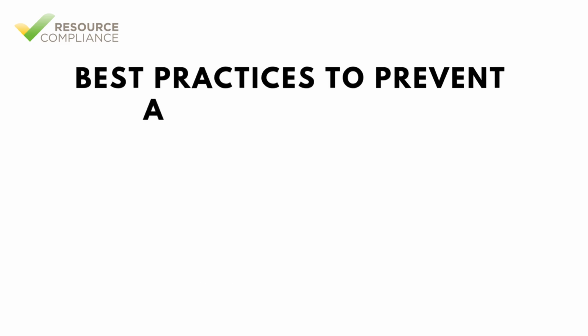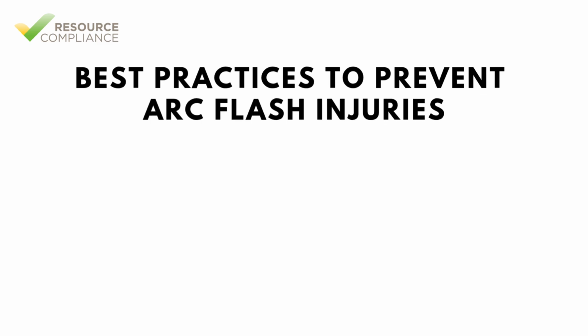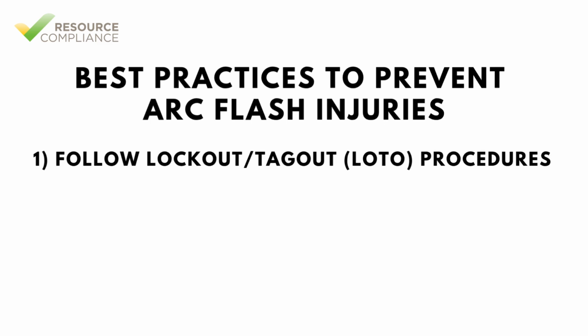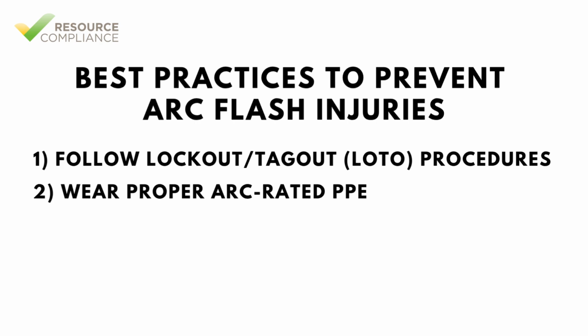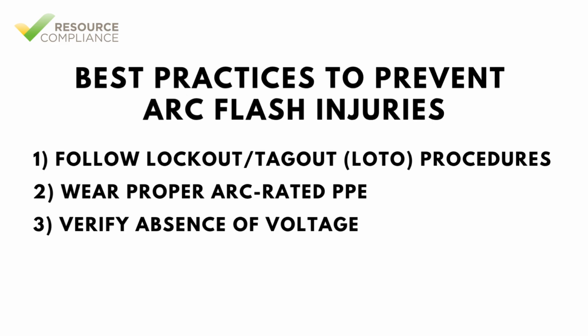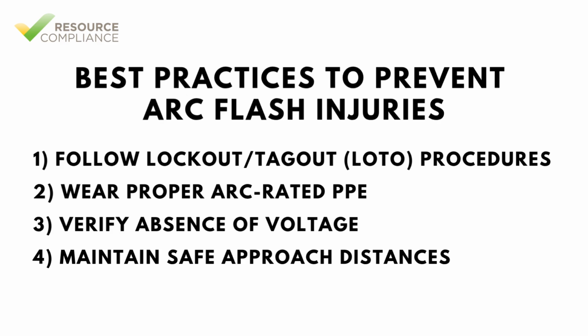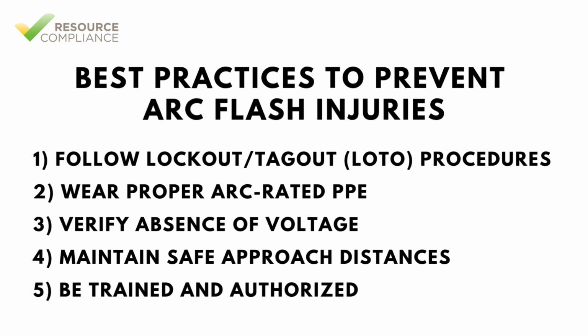It is important that proper precautions be taken to prevent arc flash and electrical injuries. Always de-energize equipment before opening electrical enclosures or performing service. Use clothing, gloves, face shields, and hearing protection rated for the equipment's calculated arc flash energy level. Use a properly rated meter to confirm the circuit is de-energized before starting work. Respect the limited and restricted approach boundaries defined in NFPA 70E. Only qualified personnel with arc flash safety training should perform electrical work.